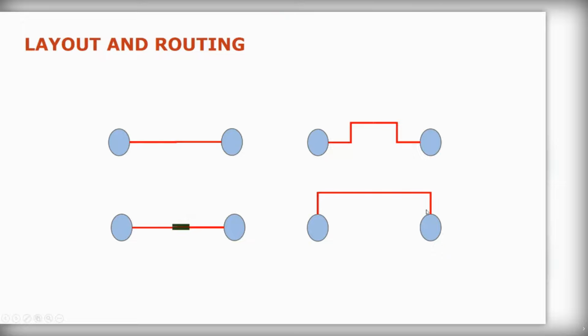Another way you could do it altogether is by this nozzle being at the bottom or looking to the bottom of the screen, and then you would zigzag all the way around the screen, and that would give a lot of flexibility to the pipe. So hopefully you're getting the point. If you can imagine pushing on this pipe or pulling on it and it moving nicely like a spring, then you will have fewer issues with thermal expansion. If it is already taut like a string on a guitar, then there's not much you can do with it.